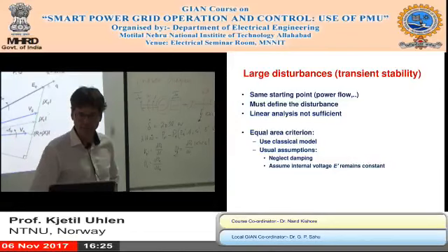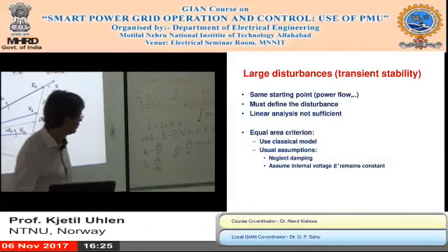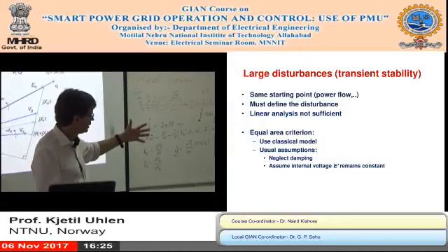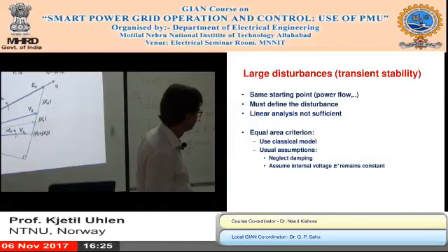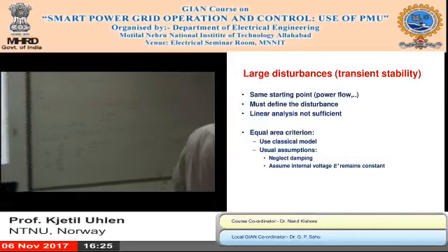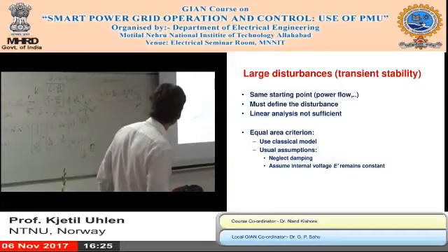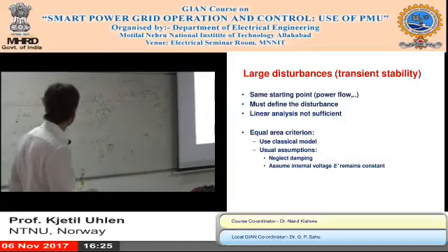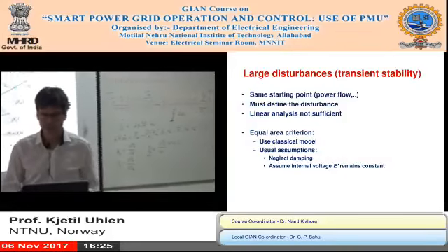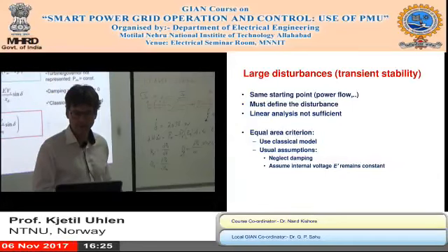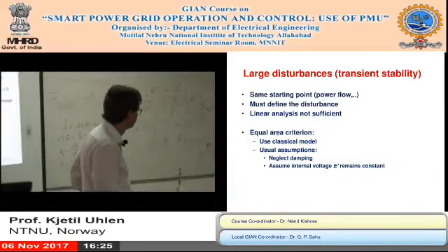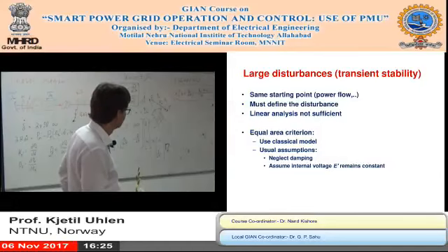And you often do the classical modeling, so instead of having separate xd and xq, we only refer to the transient d-axis reactance. It should be the transient here. And if you do that, it's simple, and the internal voltage, the transient voltage, is constant.